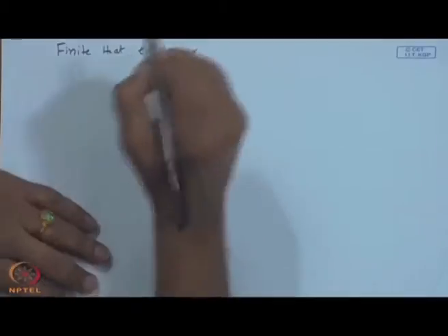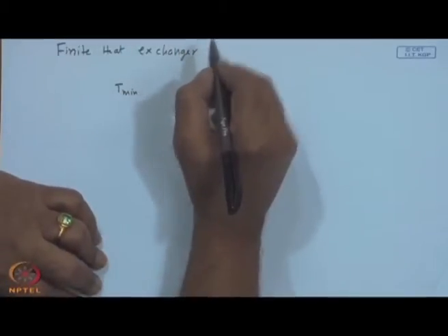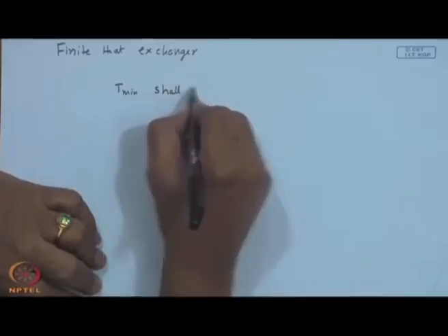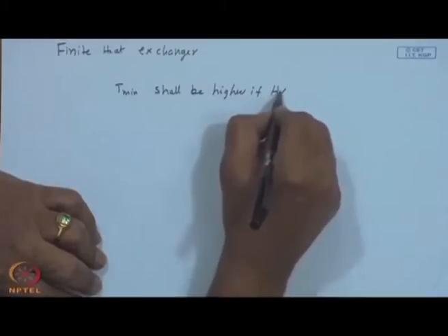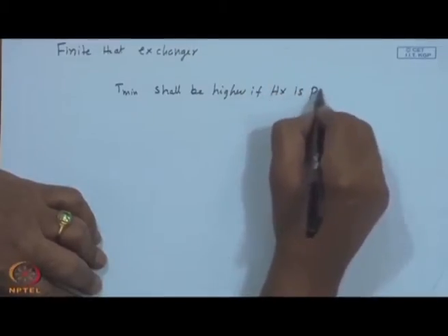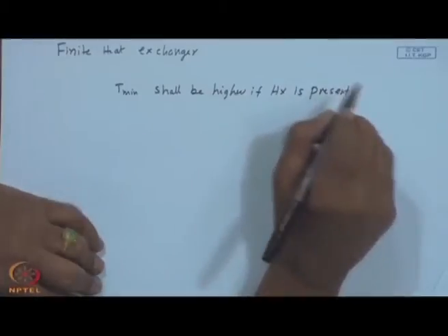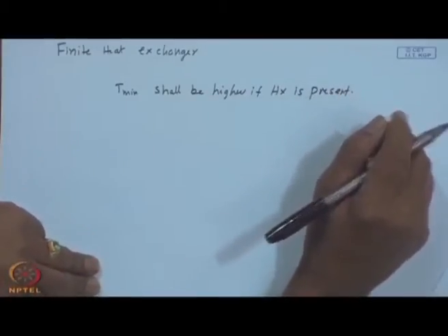So, if you think about it in the backflow, the T minimum, the temperature at which the energy is to be delivered by the collector, shall become higher if a heat exchanger is present. That will be some delta T required, that delta T reflects in the tank temperature, that tank temperature reflects in the T minimum or the outlet temperature from the collector, which needs to be delivered in order that it finally supplies energy at the originally desired T minimum.